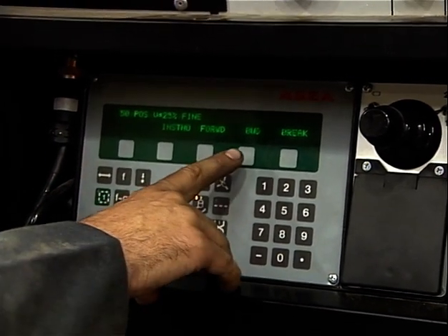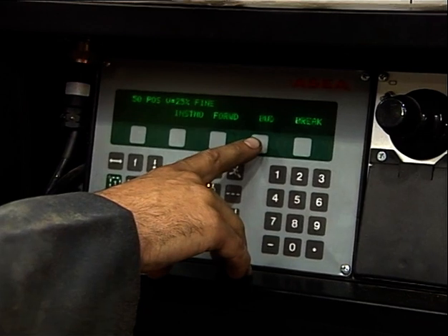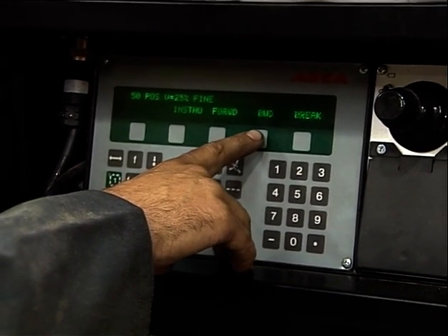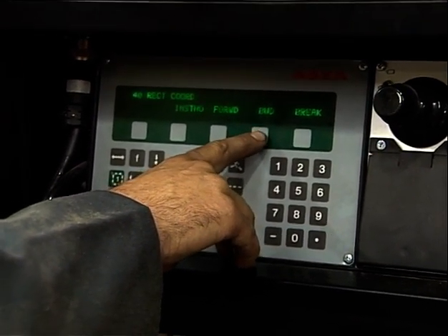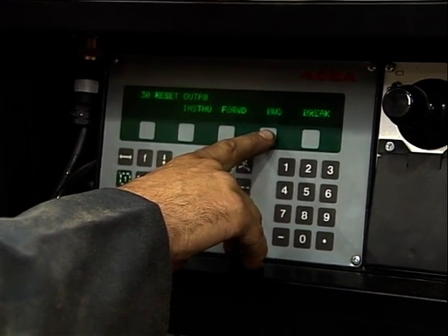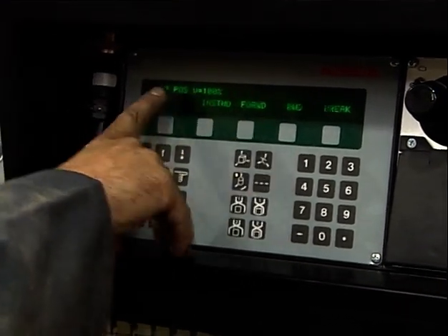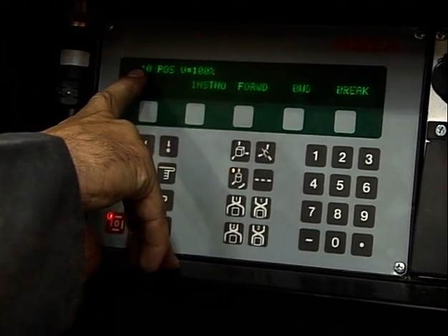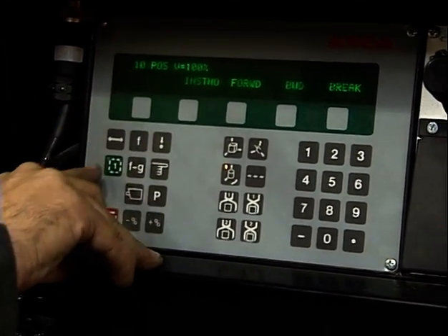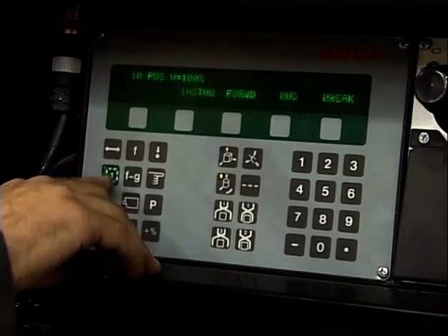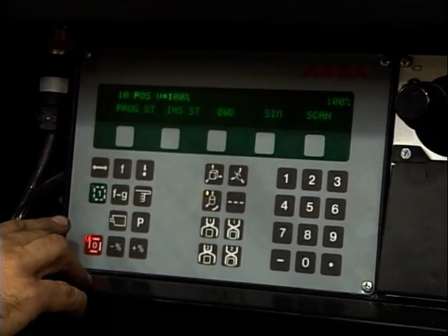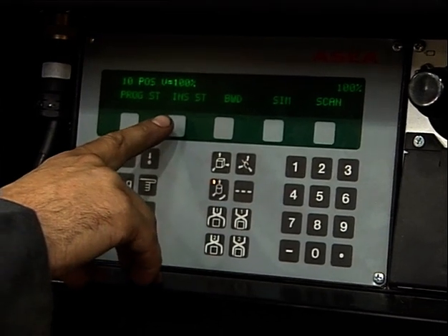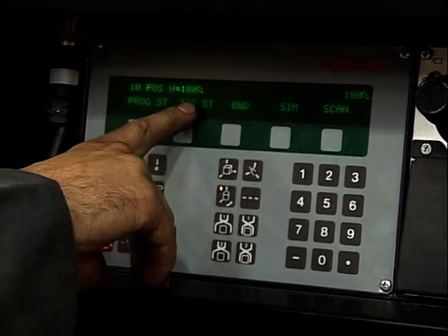Because you are on table 1, you must go until instruction number 10. 30, 20, 10. You must execute this step number. Therefore, you push on the start button, 1 on the teach panel, and you execute one step. Therefore, push on instruction step.